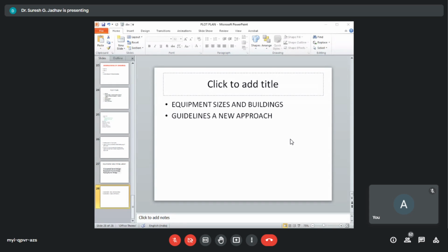For reactors with agitators, a lifting beam shall be provided for agitator renewals. For vendor requirements, maintenance space as recommended by them shall be provided. Equipment layout shall indicate the position of utility stations, safety showers and eye wash. Equipment elevation shall be arranged to ensure gravity flow where specified.